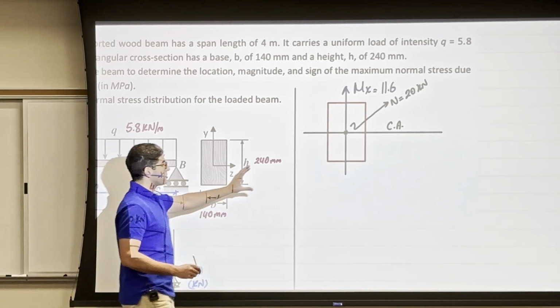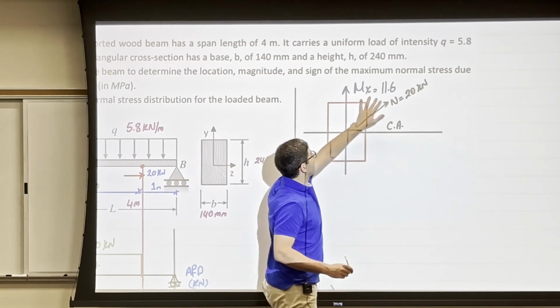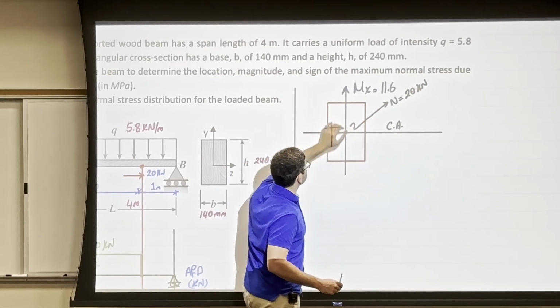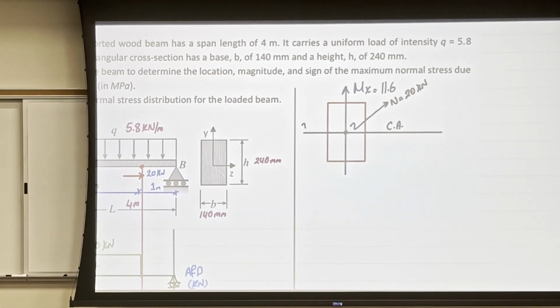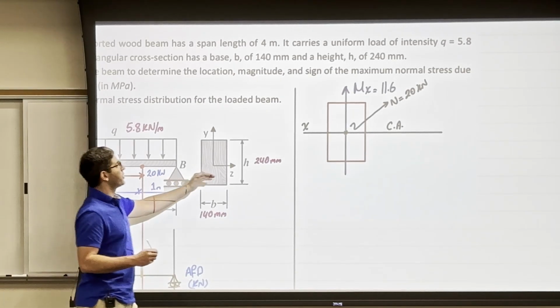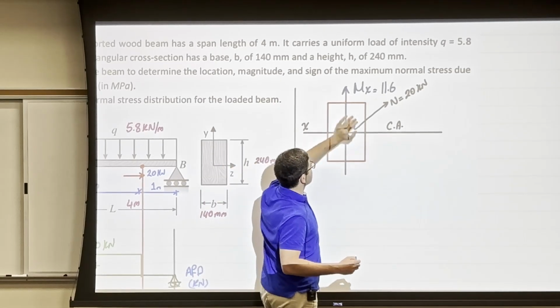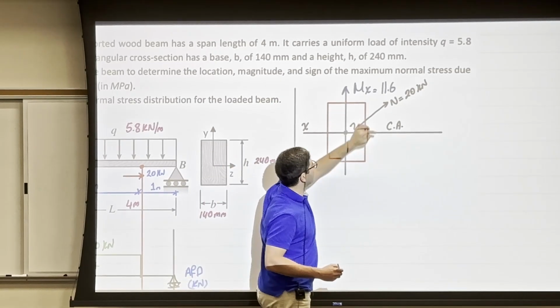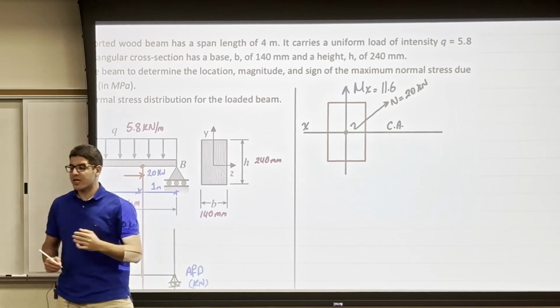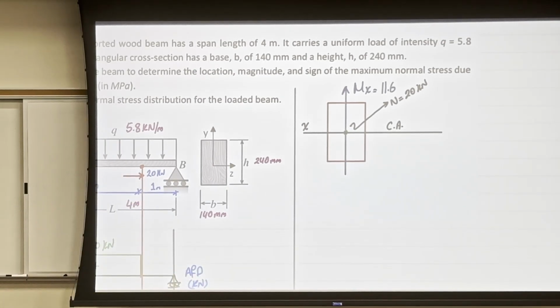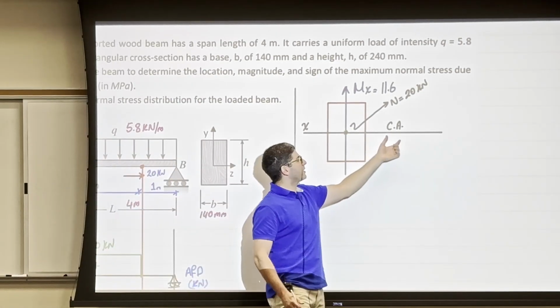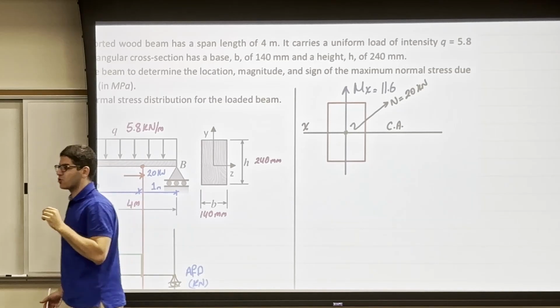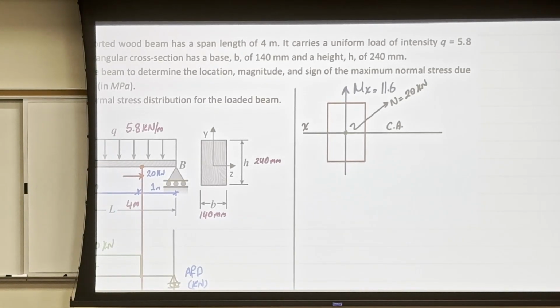So I have a cross section where Mx is moment around x. This is the x-axis, for example, and at the same time, it's the centroid. I have a moment, and then a normal force of tension equal to 20 kilonewton. So I drew now the bending moment up, and let me assume at the beginning that the neutral axis coincides with the centroid. For sure it doesn't.